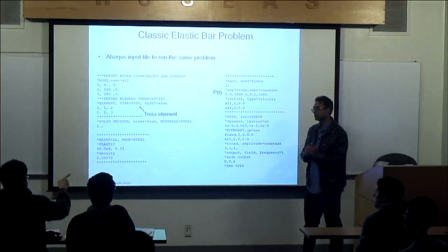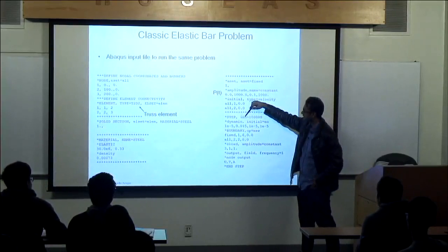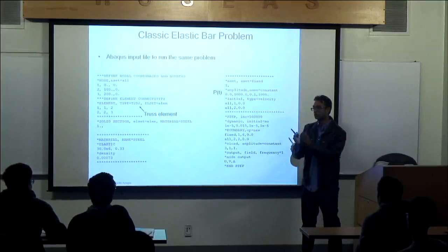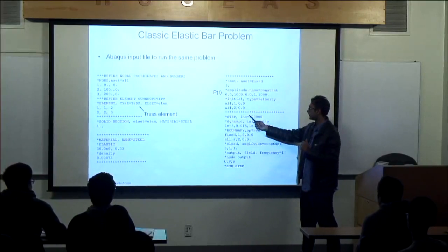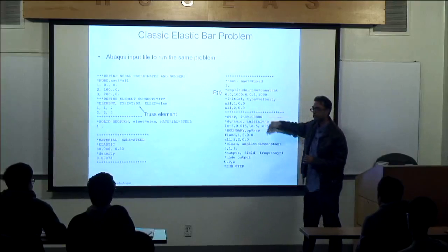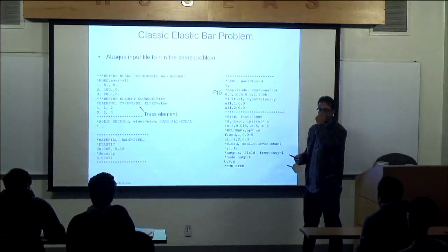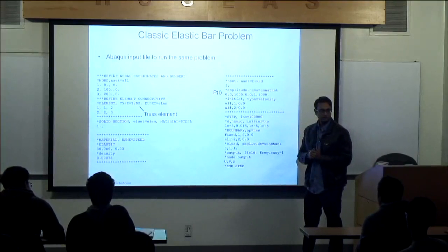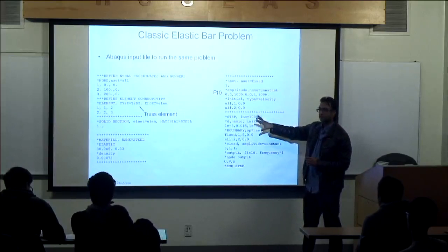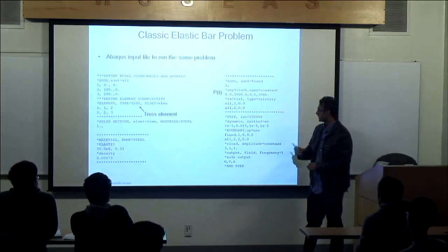There's a question. What is inc equal? Oh, Abaqus has a default of 100. So if you run the analysis in more than 100 time steps, it will stop. So I just overrode that, made it a large number. It was just to override it. But in the GUI, when Leonardo shows you on Friday, maybe you'll see how to do it there. I still do things by hand. Okay, I'm not as familiar with the GUI.